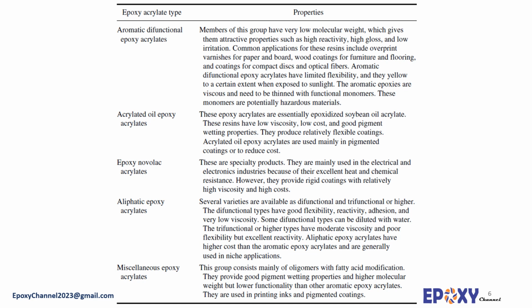In most UV curing systems, the UV light reacts with the UV initiator or photoinitiator to generate free radicals, which in turn trigger the polymerization. Sensitizing might be necessary to be combined with the UV initiator in UV curable systems. Free radicals can also be directly generated by high voltage electron beams and used in free radical polymerization, which yields a cross-linked molecular network. In this process, there is no need to use initiators.